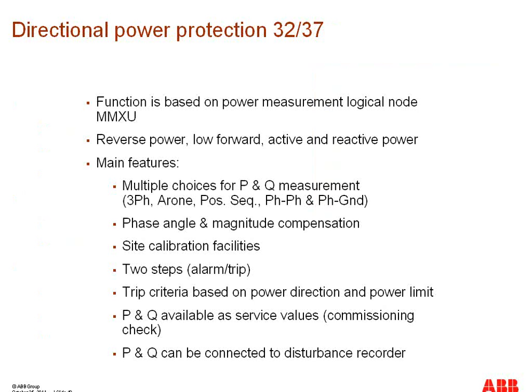Multiple choices are available: it can be three-phase, Aron, positive sequence, phase-to-phase or phase-to-ground quantities, and these quantities are used for directional power protection.